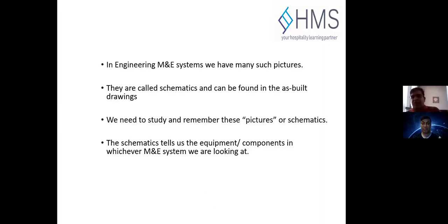If we talk about the fire life safety system, it's the same. If you don't have the schematic drawings of your fire alarm system, when you go for your license renewal, the first thing they will ask you is, show me your schematic drawings. So these are very key components and key systems which you need to really know, your schematics, and they have to be stored in your secure areas.